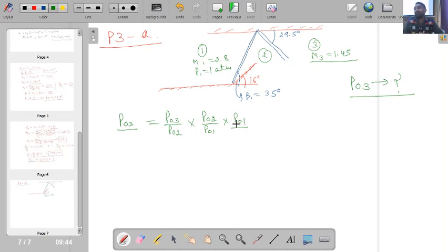But when we calculate stagnation properties, because these are not specific to a particular component, ultimately the complete Mach number comes to rest, not only a single component. The other component also comes to rest. So that's why we cannot directly utilize the relations we use for the normal shock wave.